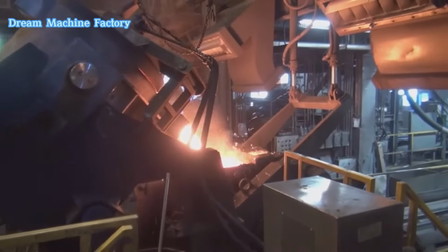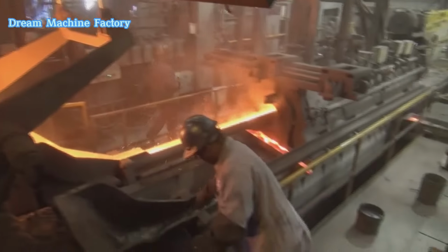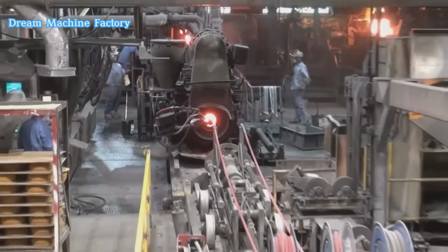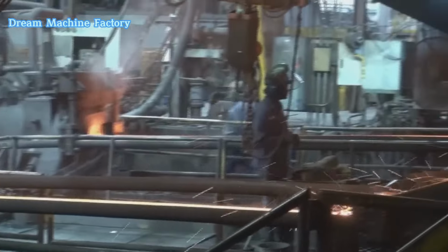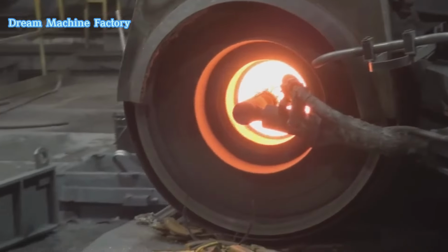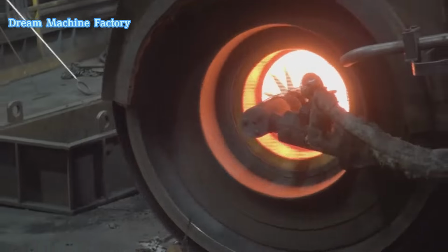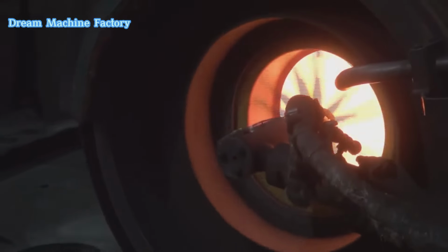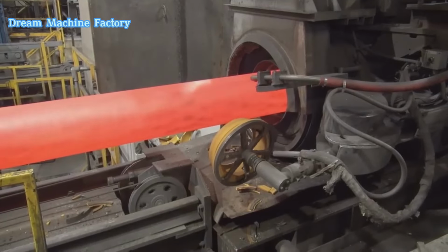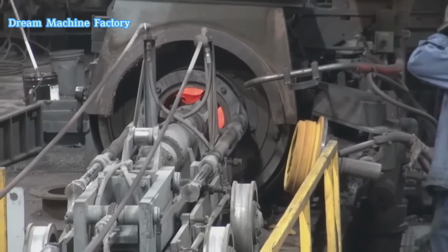Centrifugal force created by the rapid spinning of the mold pushes the iron outward, ensuring an even wall thickness. The peened surface on the inside of the mold helps the iron adhere properly, preventing splashing and defects. As the iron cools and solidifies, lighter impurities, such as slag and gases, are forced to the inner surface of the pipe, where they have minimal impact on performance.